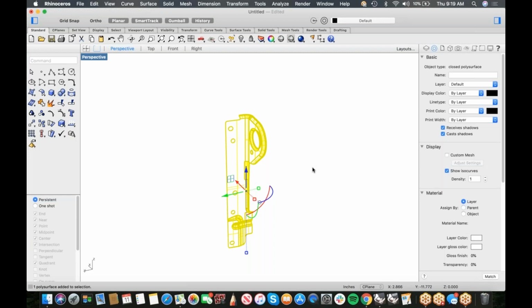The file out has to have the same tolerance of the file going in to the other package. So if Pro-E's tolerances are 0.00002 millimeters, you have to set your tolerances to 0.00002 millimeters or whatever so that they match, right? The tolerances from Rhino going out have to be set before you touch this file. You have to model to those tolerances in order to go out to have it be successful. Otherwise, you got to go through all sorts of fixing stuff when you get into Pro-E or into SolidWorks.